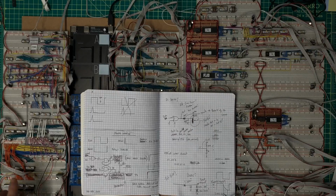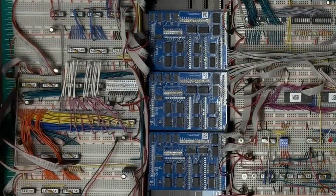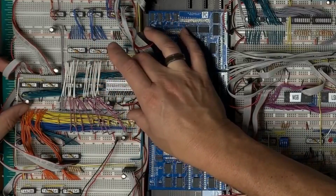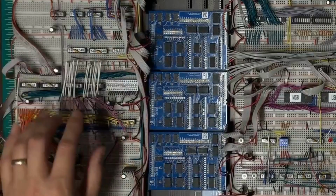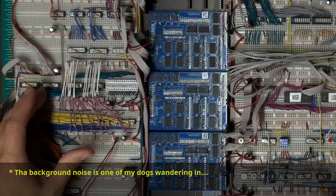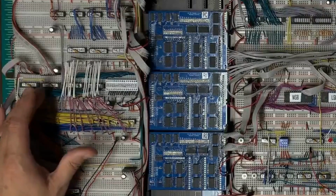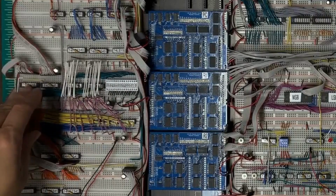All right, so with that said, I should be able to now go and figure out how to replace these bits so that I get correct output. Getting into this, pretty much everything that touches this particular board is going to have to change. So I need to put a line driver to drive the LEDs. I need a line driver to drive what's effectively an ALU bus onto this latch, which is then going to drive out onto the main bus. And so all of this wiring is going to change.